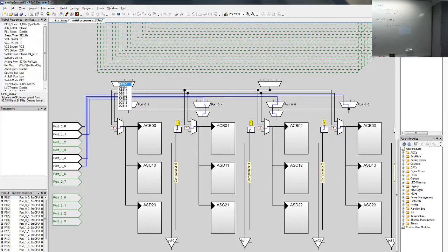So you can have, for example, an oscillator circuit on the digital blocks, actually a down counter, and use that as a clock signal to these switch blocks on each row. Sometimes you need to have a specific frequency to operate the clock. Then you would make the clock on a digital block and connect it here.